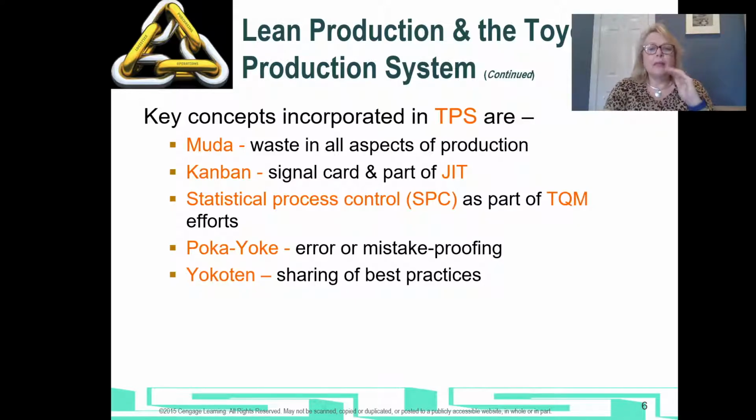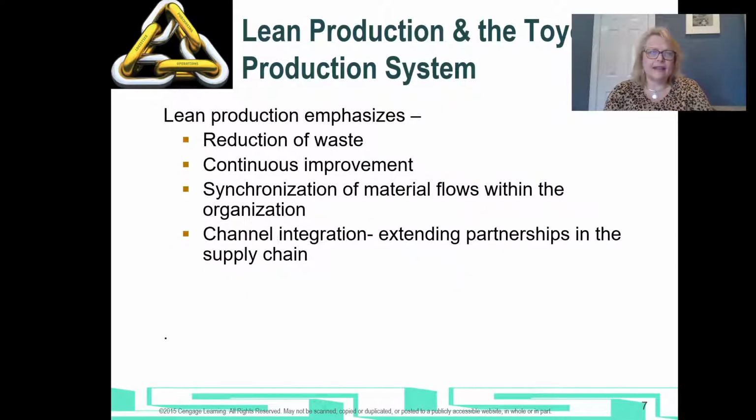That's Poka-yoke. Making it so that when the manufacturing is done or the assembly is done, there is no way that you can do it the wrong way, because there's either a fixture in place to make sure that you slide it in perfectly or something like that. But that's what the concept of Poka-yoke is. That definitely is on your test. And then Yokoten is sharing of best practices. So if you have a way to do something that's faster or that is mistake proof or that produces a better product, you should share it so that other people at either other workstations or in other parts of the business can use that same idea.